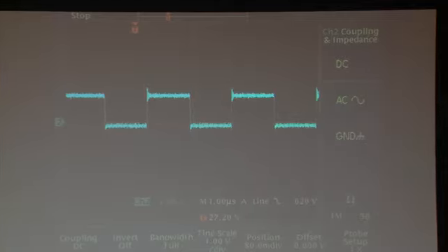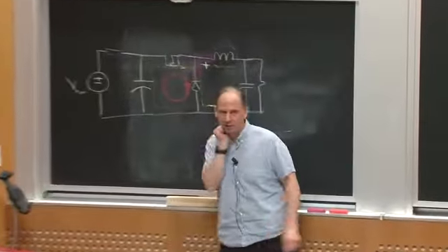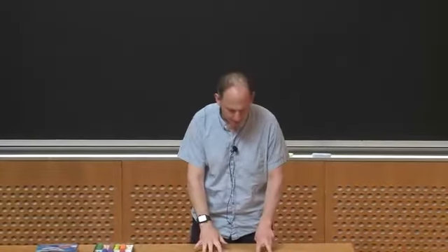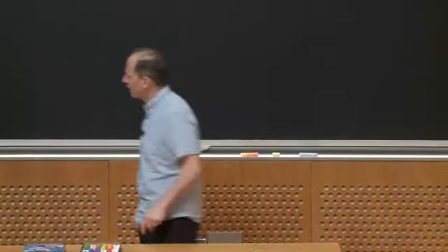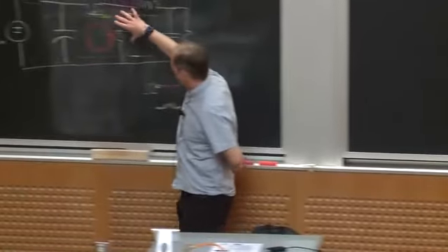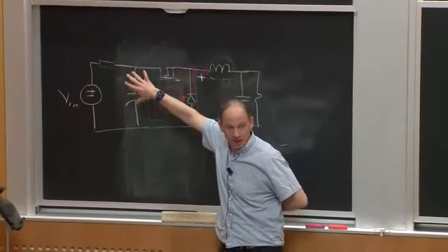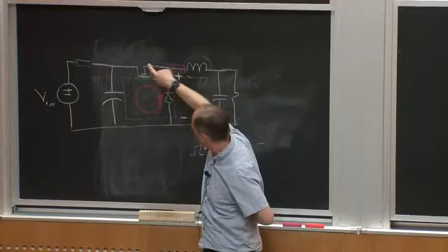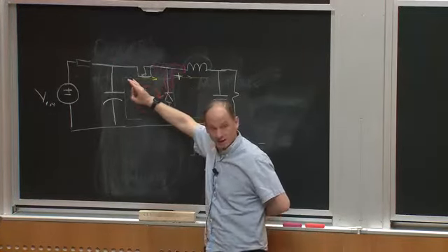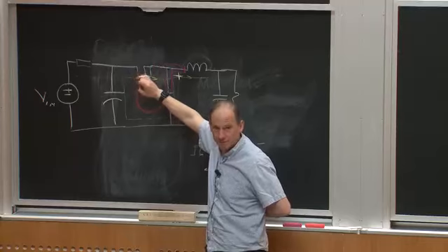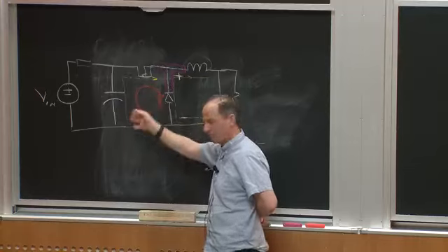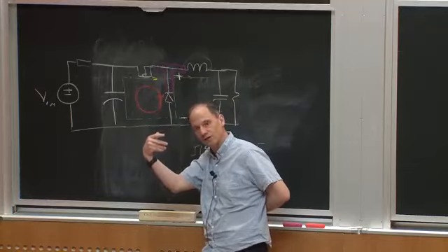So suppose I want to think about reducing the inductance of my loop. What does that mean in practice? Well, it means that I certainly want to place these three components close together, such that if I think about the current flowing around in this loop, it forms a very tight area. That's one way to think about it. If I imagine the AC current circulating this loop, how much flux is it throwing out in the world? And that relates to the inductance.